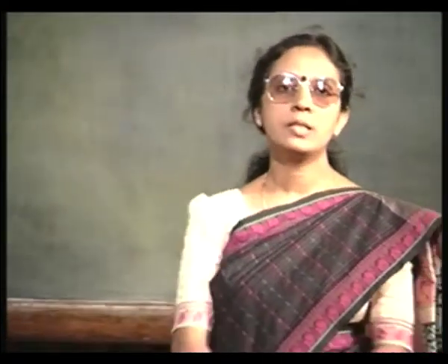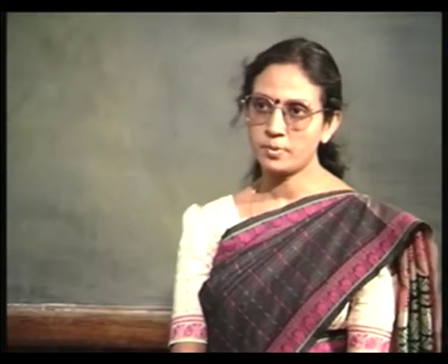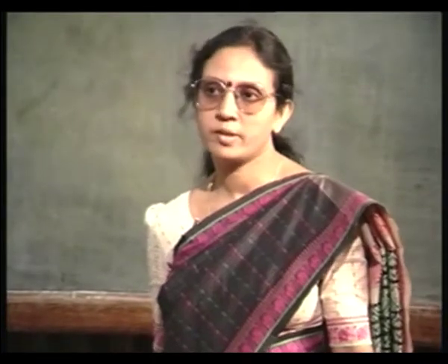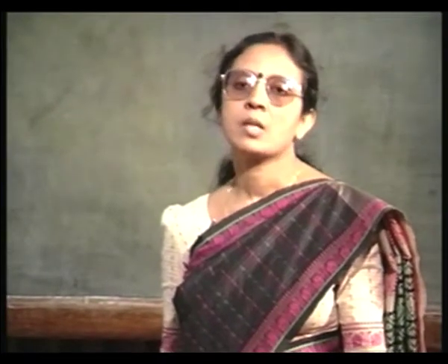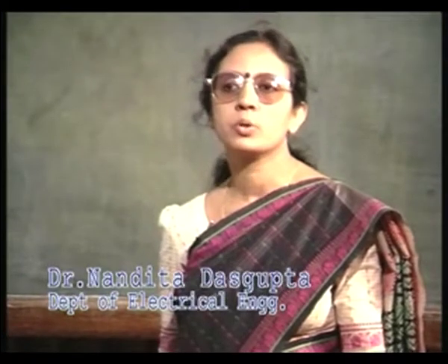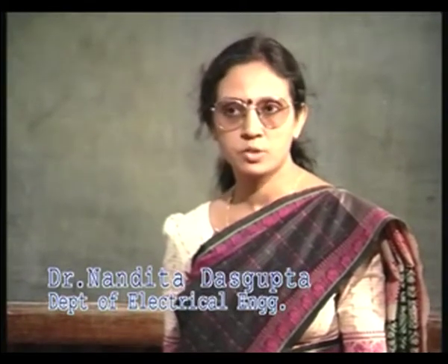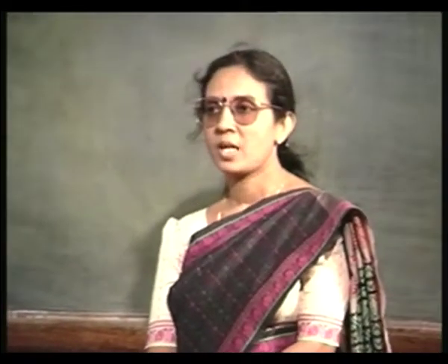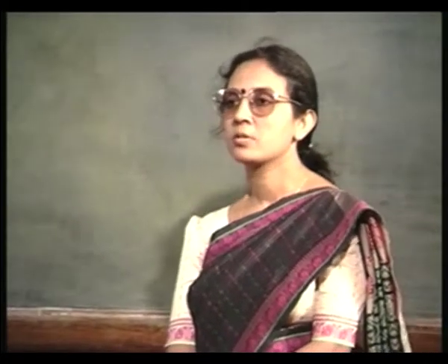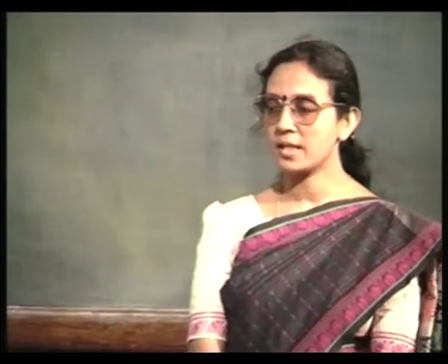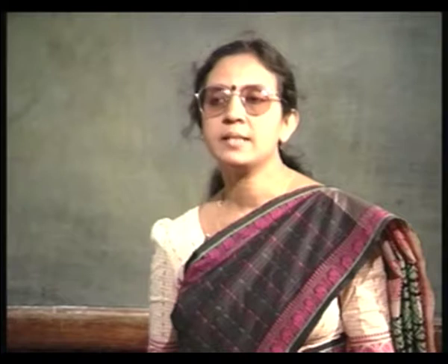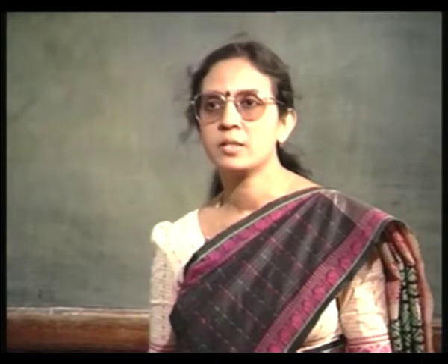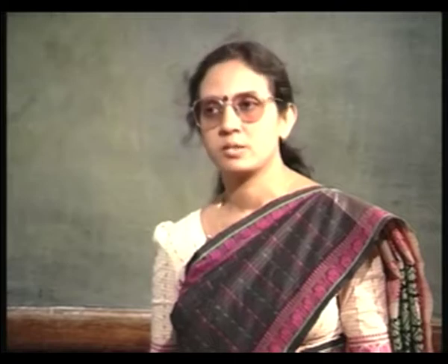Well, you know, diffusion is a high temperature process. The temperature ranges from say 800 degree centigrade to 1200 degree centigrade, and it is carried out in a fused quartz tube. Inside a fused quartz tube, we use a furnace, and inside the tube the silicon sample is placed in a quartz boat, and then it is exposed to the ambient in which the dopants are present.